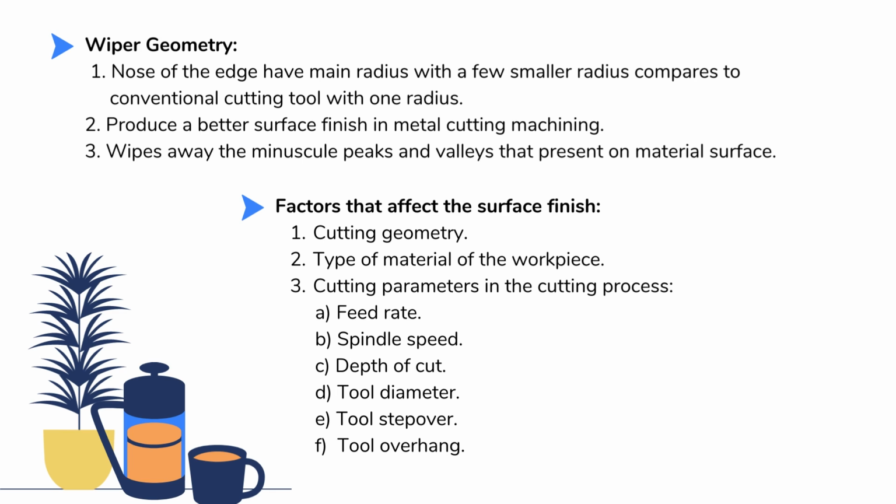There are a few factors that affect the surface finish, such as the cutting geometry, the type of material of the workpiece, and the cutting parameters, such as the feed rate, spindle speed, depth of cut, tool diameter, tool step over, and tool overhang.